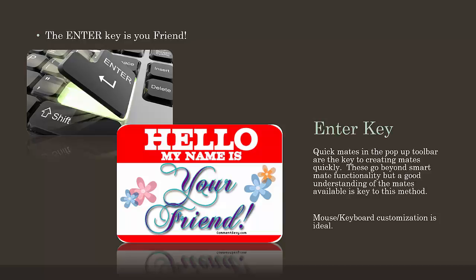Yeah, if you're doing a smart mate, so you get two faces that go face to face as opposed to you want them facing the same direction or vice versa, one of the things that I've learned over the years to get around that is I will orient the part so that that's the obvious solution that SolidWorks can pick. That's what I say in my training classes as well too. I'm like, just do it this way. It puts all the burden on the program.